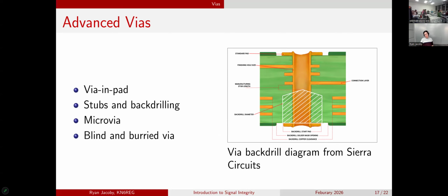Also, you might be thinking, I said vias have a small series inductance. They also form a small stub on the part that's not used, right? So if we take a high-speed signal and bury down into the board, the rest of it will actually look like an open transmission line.